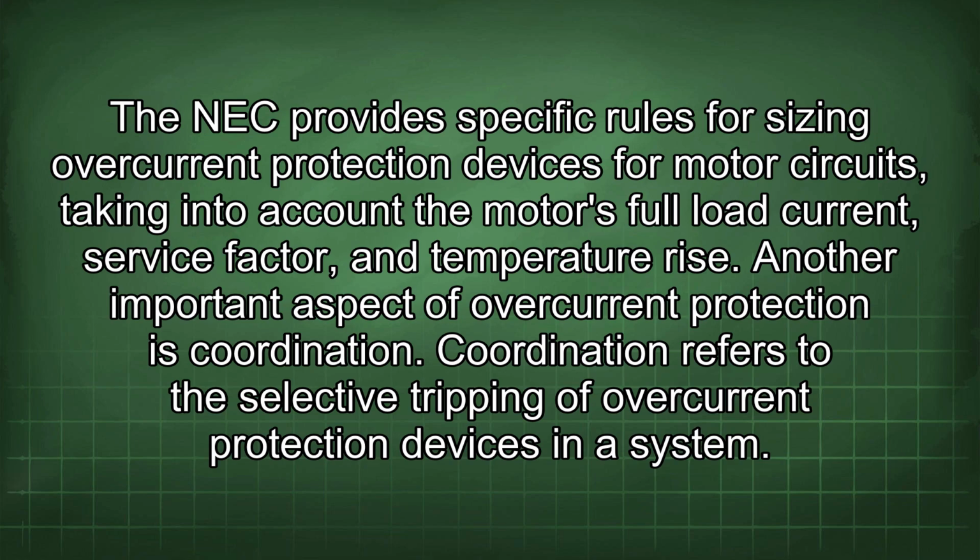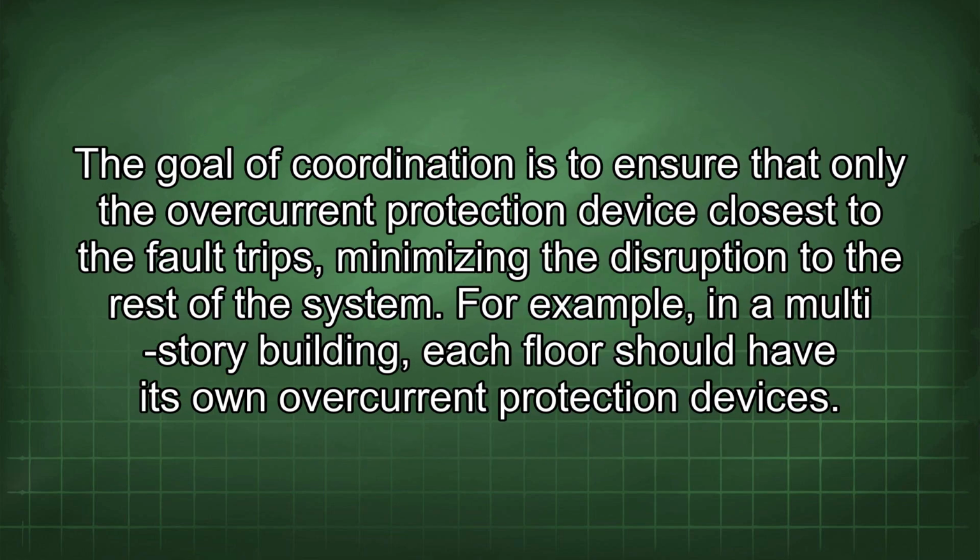Coordination refers to the selective tripping of overcurrent protection devices in a system. The goal of coordination is to ensure that only the overcurrent protection device closest to the fault trips, minimizing the disruption to the rest of the system. For example, in a multi-story building, each floor should have its own overcurrent protection devices.